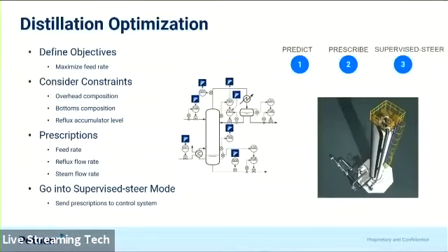This is another process that is very common in refining and chemicals, petrochemicals, distillation operations, and in some cases multiple distillation columns. They are part of a large fractionation unit. These processes are nonlinear, right? And they can benefit as well. They benefit from having a good estimator.